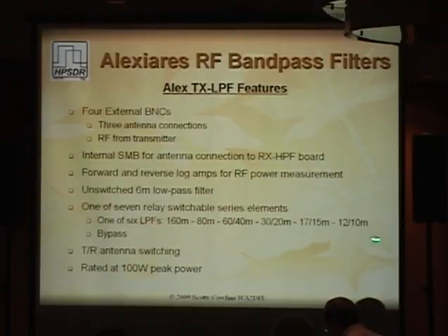And these are basically discrete filter elements, so if you decide you want to transmit on 50 meters, wherever you want to transmit in this range, the transmitter and the receiver don't care. There's not any tuned circuits on Penelope and Mercury. This is your tuned circuits. These are your tuned circuits. So you can change the components in those filters, and you can select whichever ones you want. Kind of a custom. So buy 2, and then you can make the second one custom.